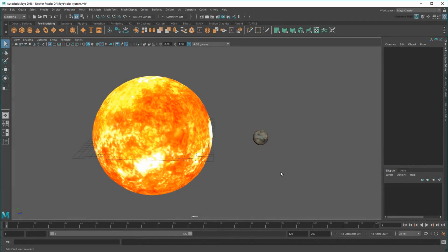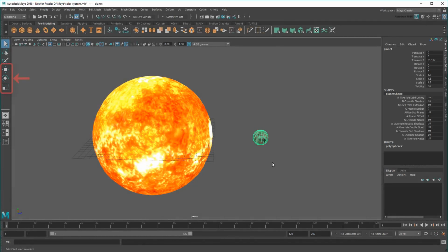So in Maya you can move, rotate, or scale an object using the transform tools in the toolbox. You can also activate each of these using the W, E, and R hotkeys respectively. Whenever you transform an object, Maya always does so around a pivot point. Even though the pivot's usually invisible, a quick way to tell where it is is by where the manipulators appear.